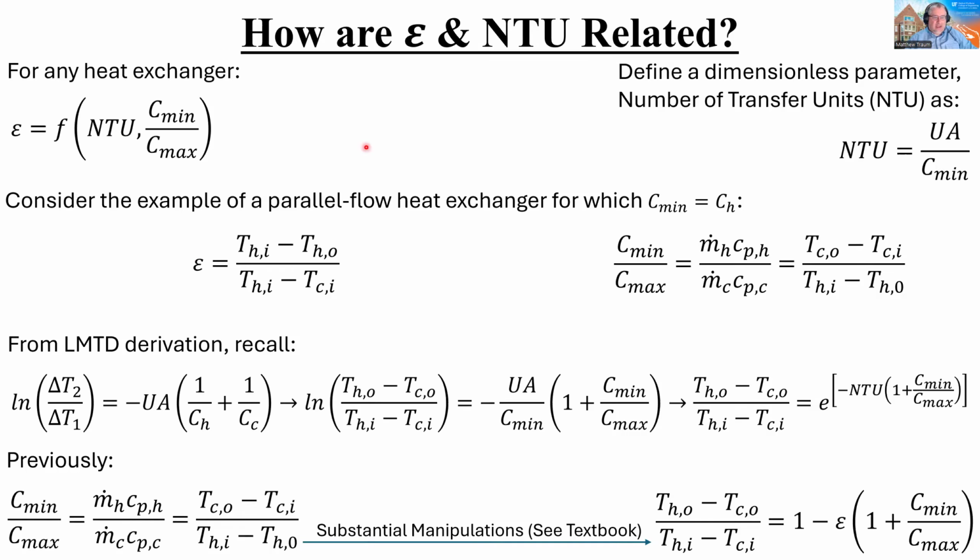LMTD is the same way though. You can do LMTD for a parallel flow or a counterflow heat exchanger, and all the math works out very easily. But as soon as you start dealing with cross flows or shell and tubes, you have to use, you guys should remember from the lecture, all kinds of correction factors, and so you end up having to do all this anyway. With LMTD, LMTD is no better than Effectiveness-NTU in this way.